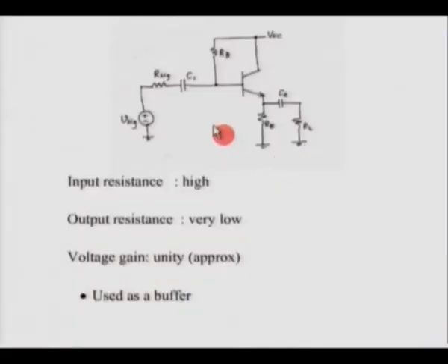The main difference being, in a voltage follower the impedance you get is almost infinite, because the output is directly connected to the negative input terminal of the op amp. The open loop input resistance gets multiplied by an extremely large value, which is almost infinite, but here the value is not that high. Again later we would see in another lecture how we could increase the value of the input resistance.